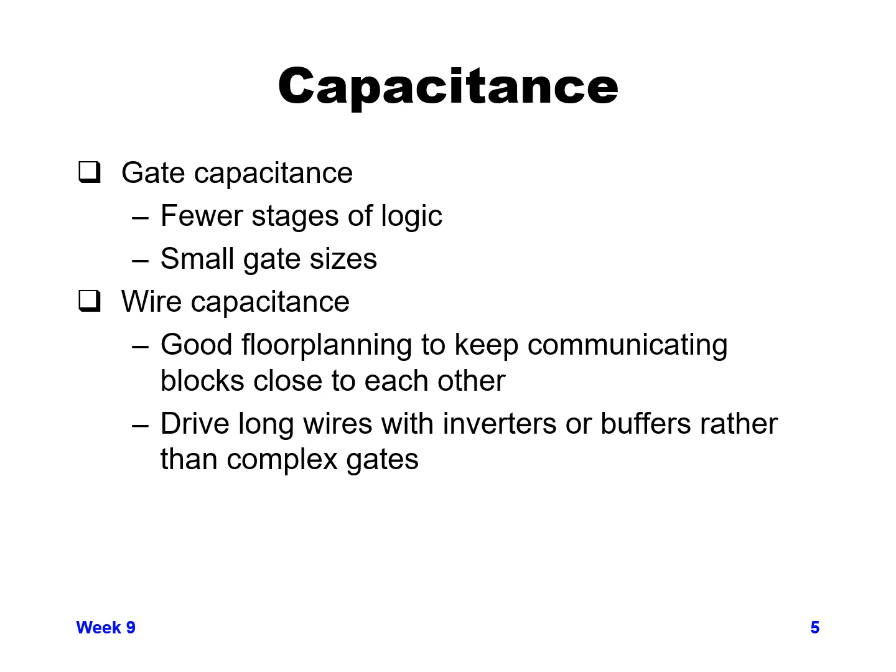If you're trying to use complex gates to drive a long wire or large capacitance, they have to be much, much bigger, and so it's not the most efficient in terms of power. Sometimes using a complex gate to then drive an inverter or buffer that drives the large capacitance can be more efficient in terms of power, even if it takes a little bit more delay to go through the gates.